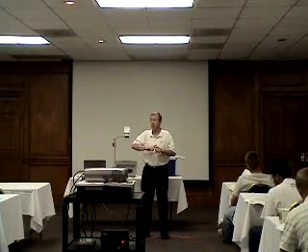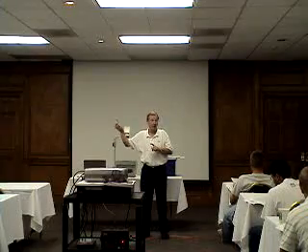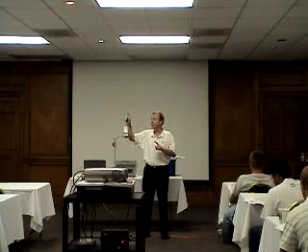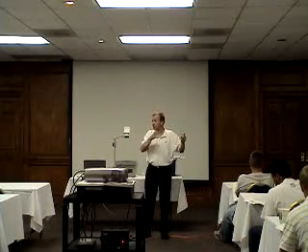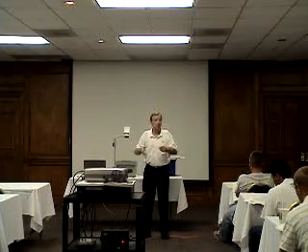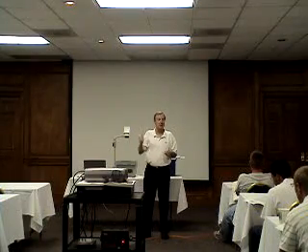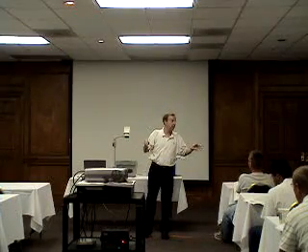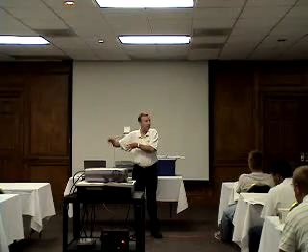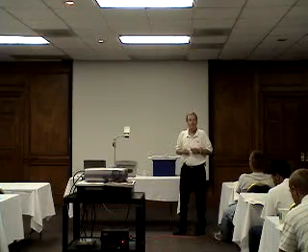It's 404 into the second increment, so that means I've got to add that 404 to 750, and it's at 1150, where you're using a cumulative tonnage, and you just continue that process. The next time, I multiply my number times 750, I add it to 1,500. The next time, I add it to 2,250. Next time, I add it to 3,000. That's all the process is. Any questions on that?